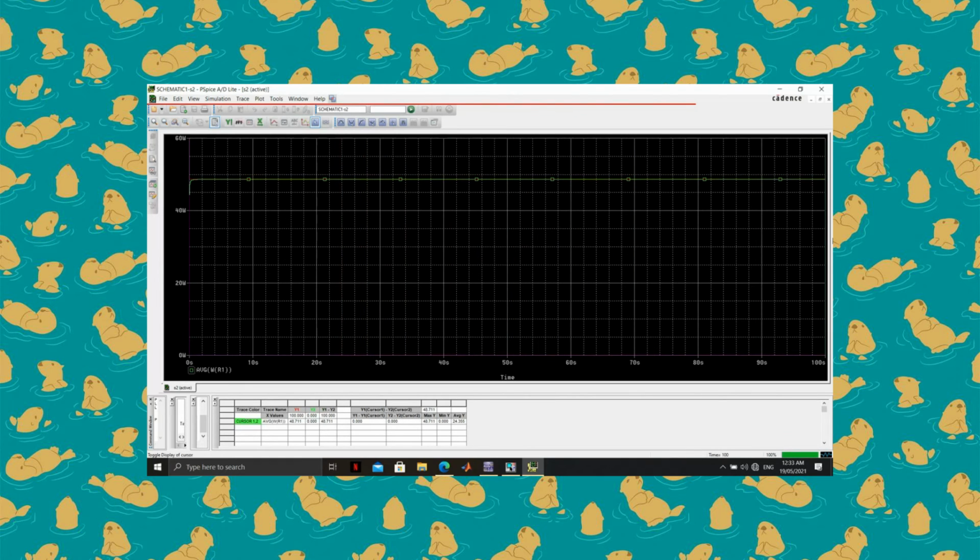At the end, you could see that the average power is 48.711 watts, which is close to 50 watts. Anywhere here, the value is close to 50 watts, remaining within the 48 to 49 watts range. There is a slow increase in power because of the capacitor charging.